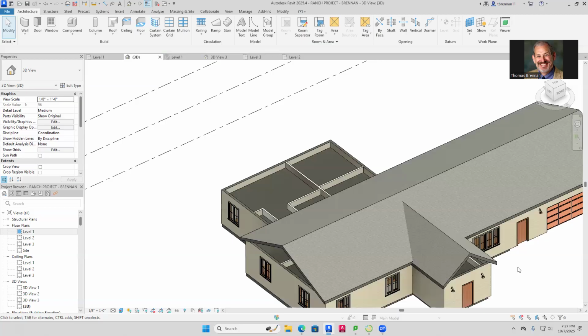Okay, that one's not visible. So zoom out a little bit. What we'll do is click on this floor, click on that one, and that's negative 6 inches. I think we said to make that negative 12 inches. Using your floor type and a height offset of level negative 1 foot. So make it negative 1 foot instead of negative 6 inches. And then the negative 11 inches should work for the other one. And it did. There you have it.